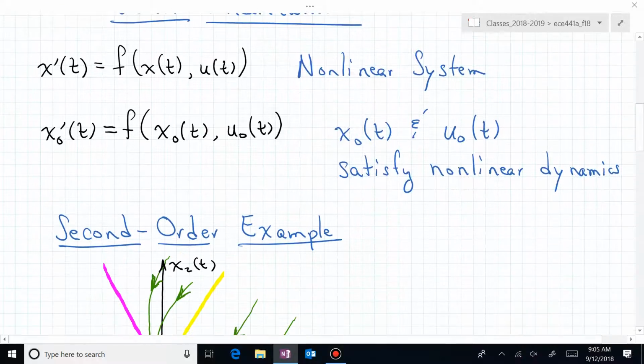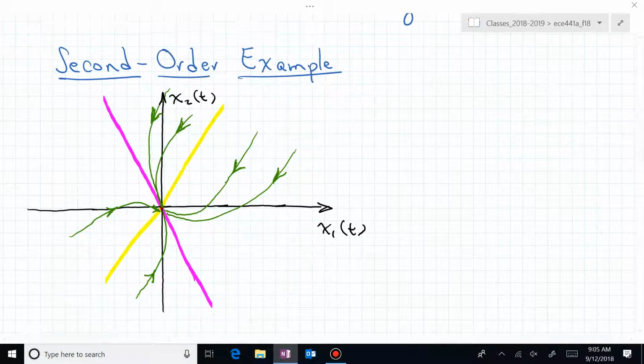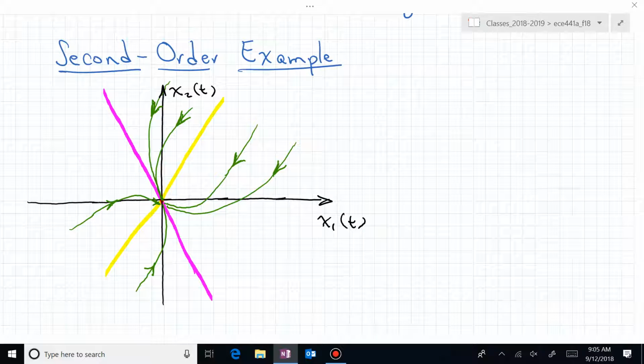And we want to work through that for a second order system. Here is maybe a visual of what I'm talking about. These highlighted lines through the origin are actually eigenvectors, and the point that you are at is away from the equilibrium condition. The equilibrium condition in this example is the origin. x1 is 0 and x sub 2 is 0. But now if you moved away from the origin, imagine you're now a little bit away on one of those green curves.